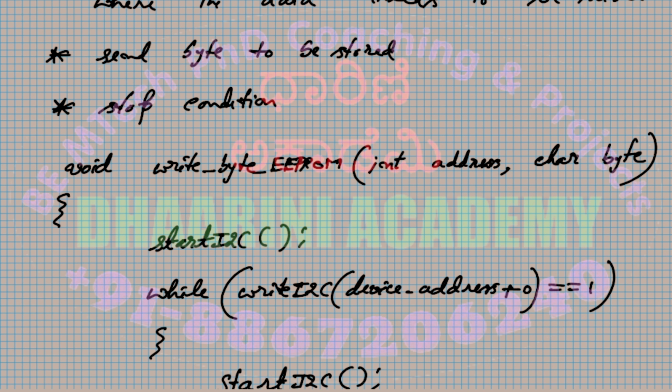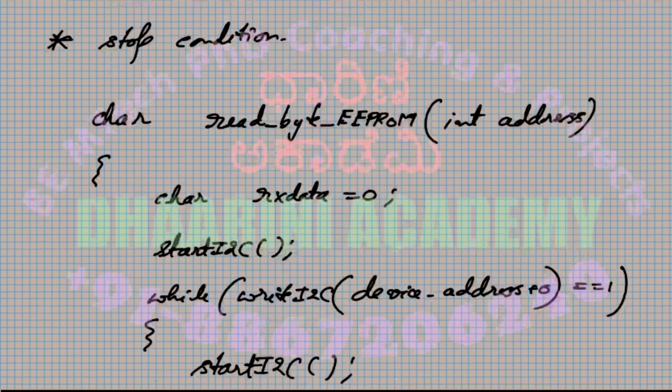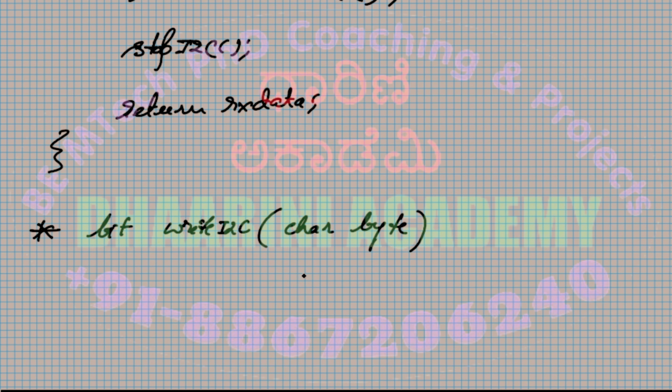That's what we missed. All right, so I'll just make that correction over here. Right, so you understood what exactly is happening. I declared that as an int, but in my write I2C function, whatever I'm sending here, I'm declaring that as a character. You see here, it's write I2C. I have to pass a character to that function. I cannot pass an integer. So that's a problem, right?